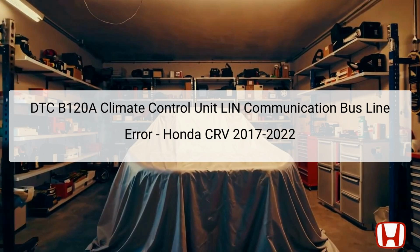The climate control unit is typically located on the dashboard and interfaces with various components via the LIN communication bus. This system allows for efficient data transfer between components, enabling proper climate control operation. The LIN bus is a vital wiring component that connects the climate control system to the vehicle's main electronic control unit, ECU. When there is a communication error like DTC B120A, it can lead to numerous performance issues in these modules. It is imperative to diagnose and resolve these errors promptly to ensure optimal vehicle comfort and function.